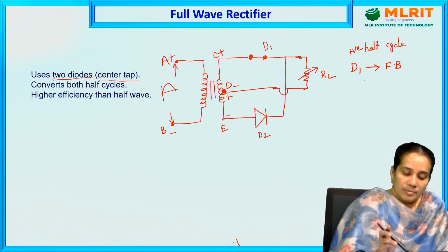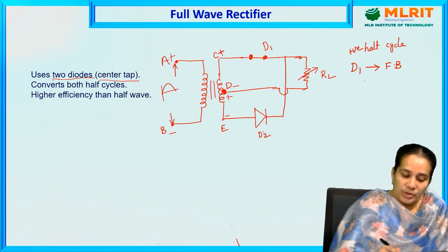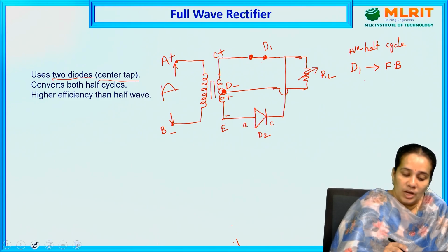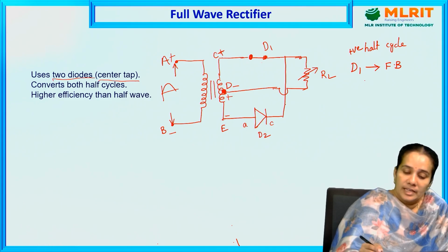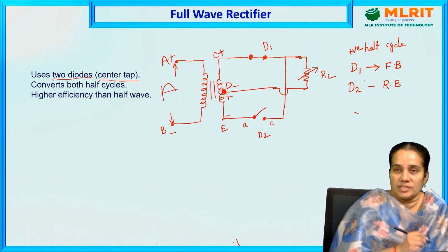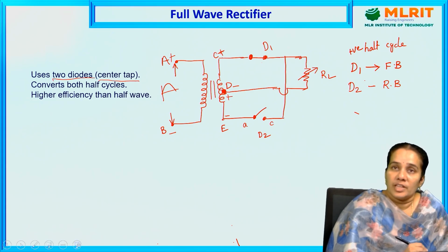Next, similarly, when it comes to the diode D2, the P-type semiconductor or anode terminal is connected to the negative terminal of the battery. When the anode is connected to the negative terminal of the battery, the diode D2 goes into which bias? Reverse bias. So what is happening in reverse bias? The diode goes into the off state. So in the off state, the diode becomes an open circuit. When it is open circuit, there is no current flow.